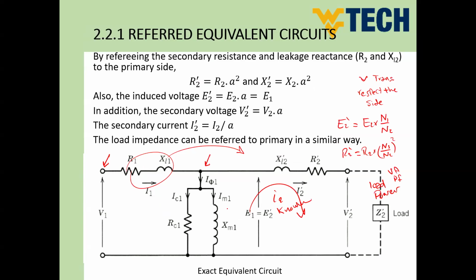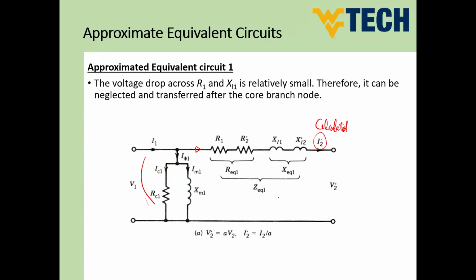However, you don't know the volt of this point, which means you have to make some circuit analysis, like nodal analysis, or make loops like that. You have a loop here, and you know the current of this one. So it's 3 loops, but 1 current is known. So by the end, you will have 2 equations.